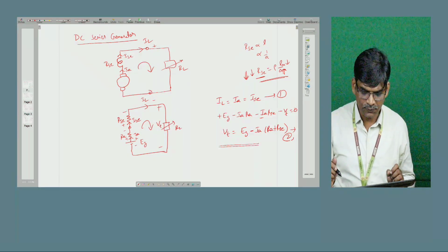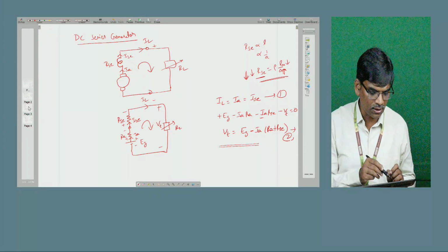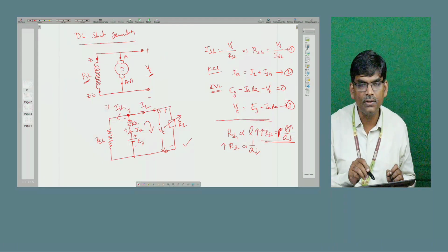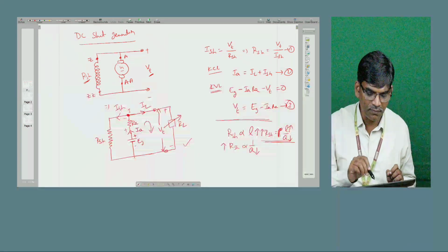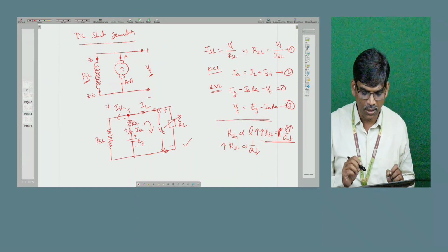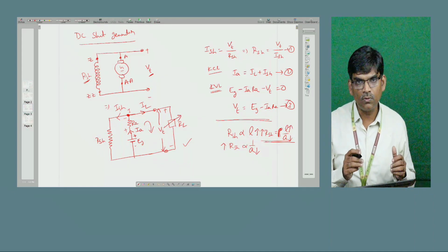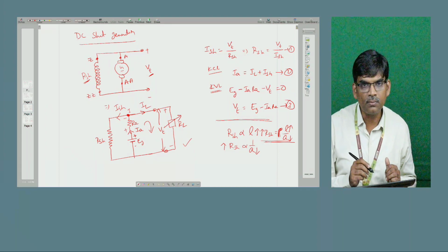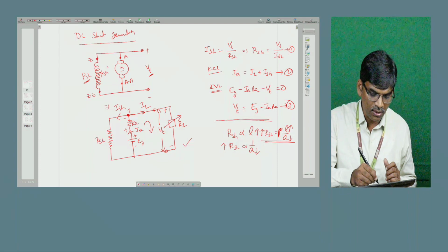So I conclude what I observed in the shunt generator. In the shunt generator, the field winding is connected in parallel with the armature winding, so across this field winding we connect the terminal voltage. It is for a low current rating, which means low cross-sectional area, and to set up more flux, by the MMF formula Ni, it uses more turns and less current, NSH and ISH.